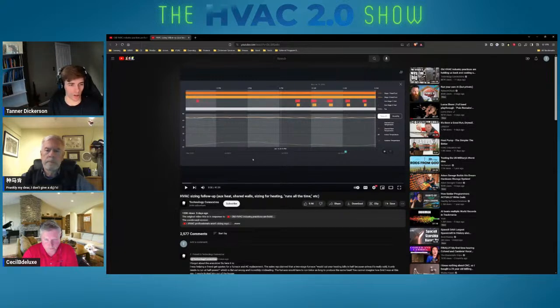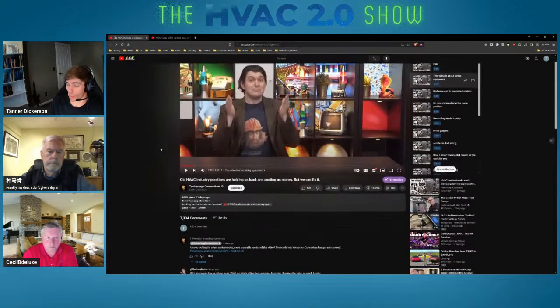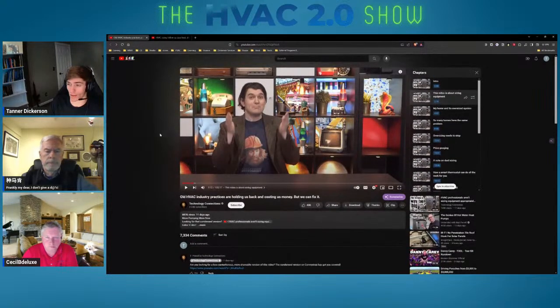X amount of energy equals, however many BTUs. And then how does that compare to my furnace? And how does that line up with the runtime data that he had on his furnace previously? And so he was able to really triangulate in on what his actual load calc is, which was pretty interesting to see, because really the conclusion of his videos was basically what we've already kind of come to, is that most systems are oversized.